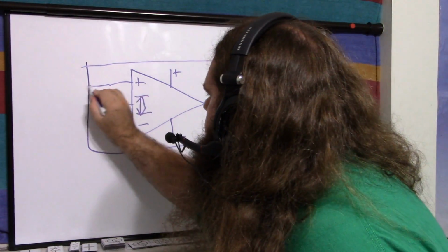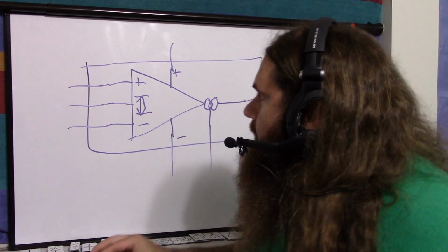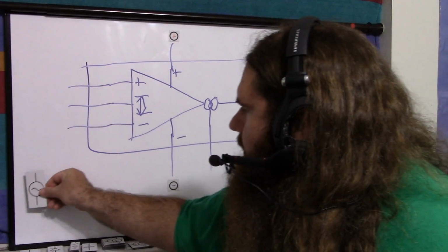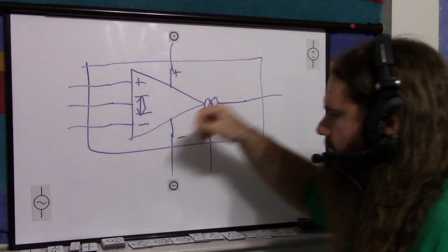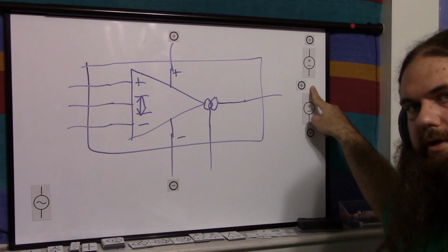And these are the pins that are exposed from the chip. All these pins. So up here, you have your positive power and your negative power, unsurprisingly. And then you have your 2 signals. Here, I'll put the little power up here so we can see it. So here's our dual power supply. We've got positive voltage, negative voltage, and the circuit ground in between.